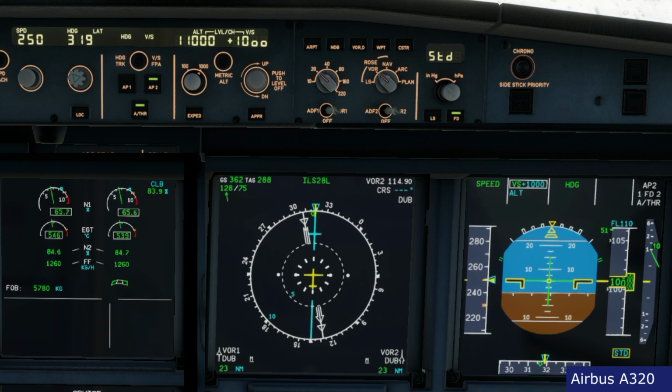The aircraft is climbing 1000 feet, alt is blue, and the thrust mode remains in speed, meaning that the thrust is managing the speed. So this is going to be a fairly smoother way of climbing. If I want to be even smoother with passengers, I could select a lower rate. It's not recommended. Most of the busy airports require at least 1000 feet per minute rate of climb and descent in terminal area, so probably 1000 feet will be the correct number.